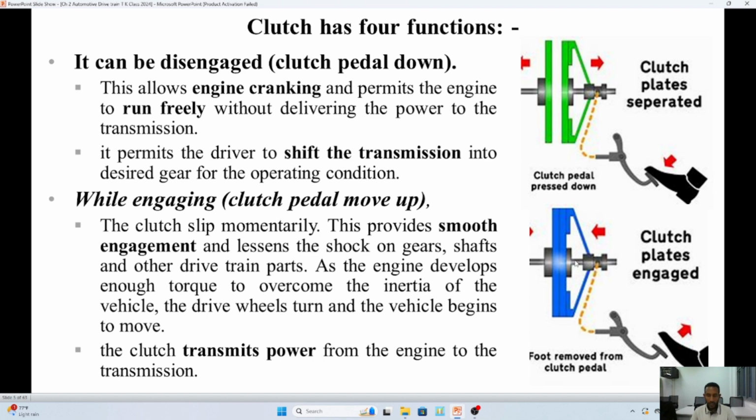So in the next part, the clutch assists with balancing when we release it slowly. And when the clutch pedal is fully released, going up, it allows the engagement of the engine to the transmission, and the engine can transmit power one-to-one from engine to transmission. After that, the transmission will reduce or increase the speed and the torque by its gear mechanism.